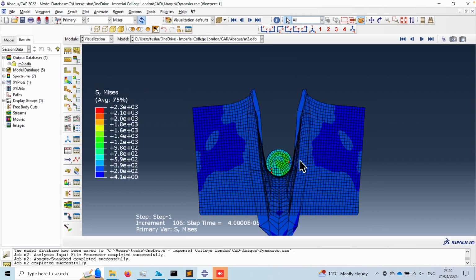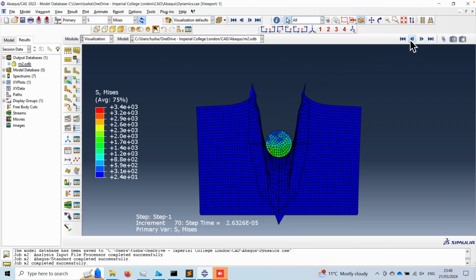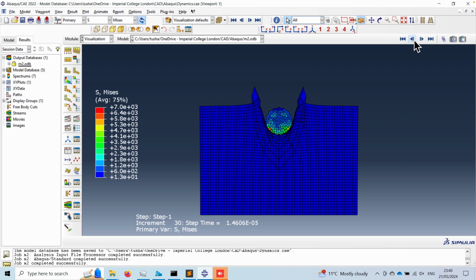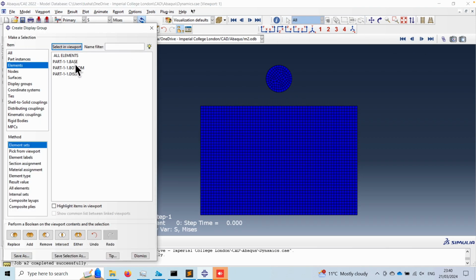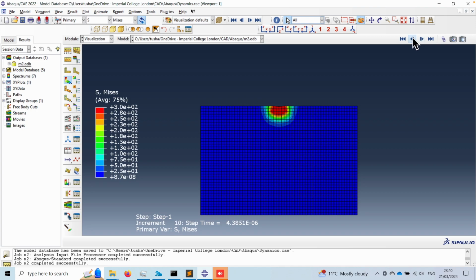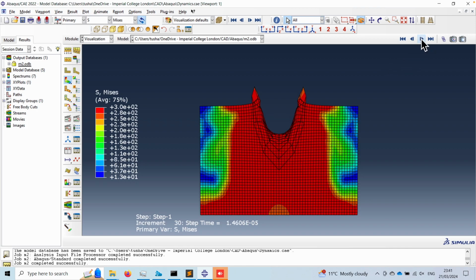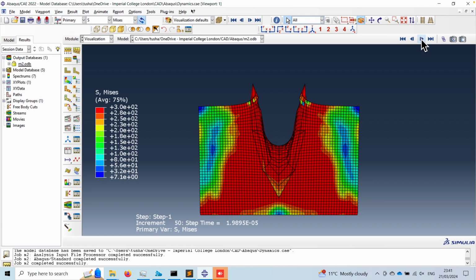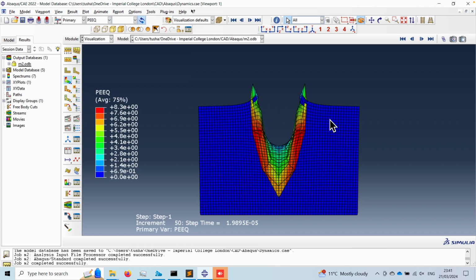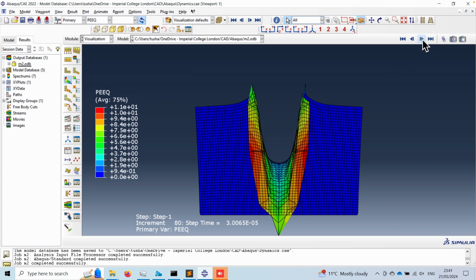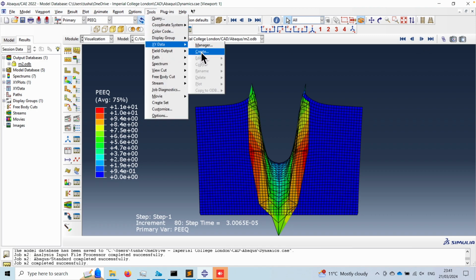Okay, we have seen the other results, like we have seen this result earlier. This is the von Mises stress we would like to see in the aluminium only. So initially at contact it is around 5 microsecond. At 8 microsecond you can see lots of stresses and penetration of aluminium by the steel disc, and of course it comes with lots of plastic strain, right.